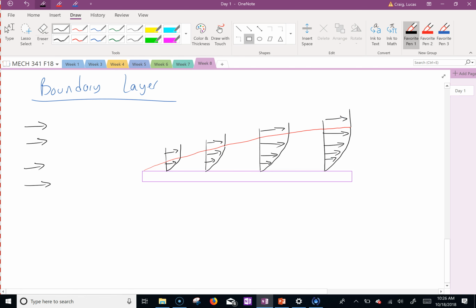Because you need to know what type of flow you are and where your boundary layers are. Yep, heat transfer did this. Anywhere from the red down, the velocity is 0 at the surface and increases to pretty much your free stream velocity, or whatever velocity is upstream, above the red. Okay?